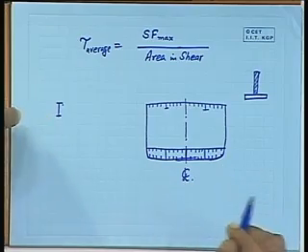Normally we consider that from the after peak bulkhead to the fore peak bulkhead, in that region, or if we want to take the superstructure, which by definition is extending from side to side, and the extent is not less than 40% of the length. So that will contribute towards the longitudinal strength. All these members we try to find out the second moment of area for.